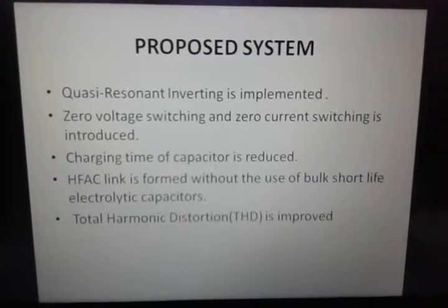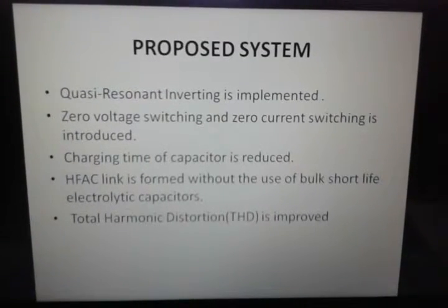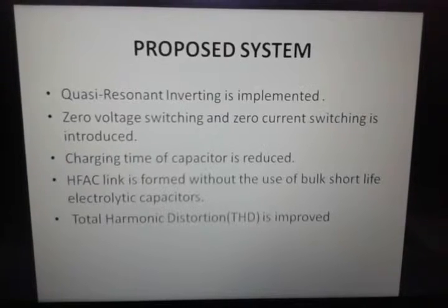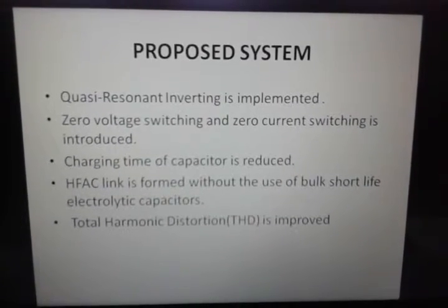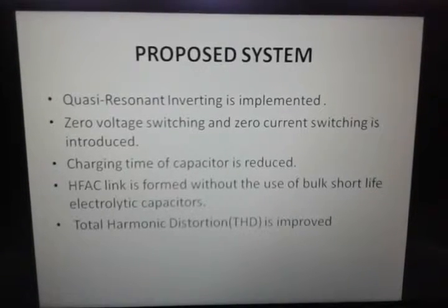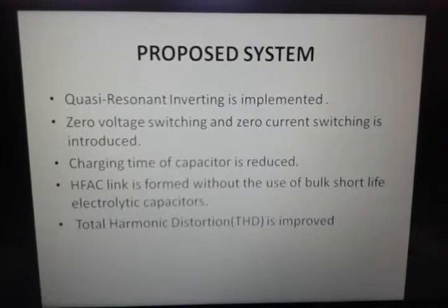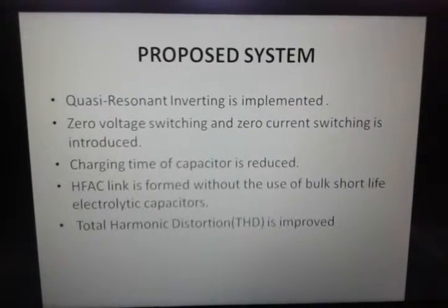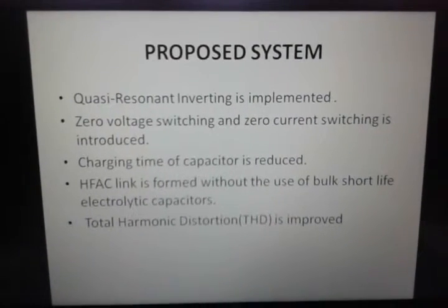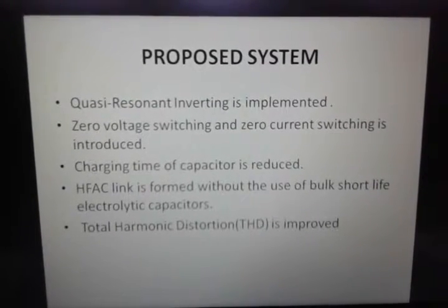Proposed system: we implement quasi-resonant inverting, zero current switching and zero voltage switching. Actually, quasi-resonance is allowed to occur just before and during the turn on and turn off process to create ZVS and ZCS conditions. In ZCS, the turn on and turn off will occur at zero current, whereas in ZVS, turn on and turn off will occur at zero voltage.